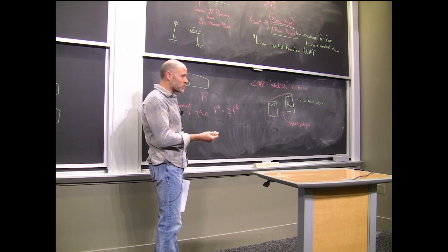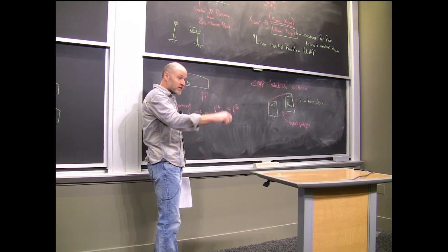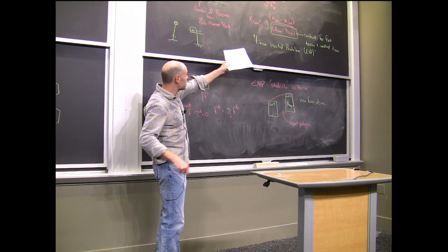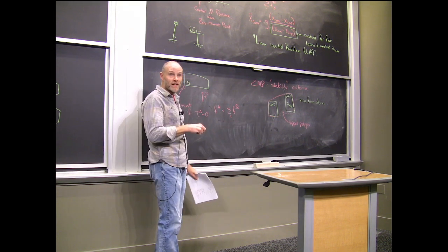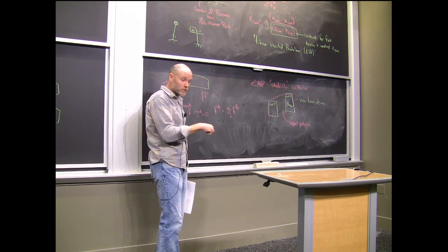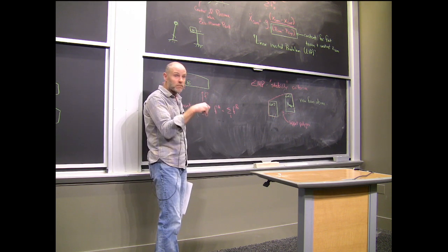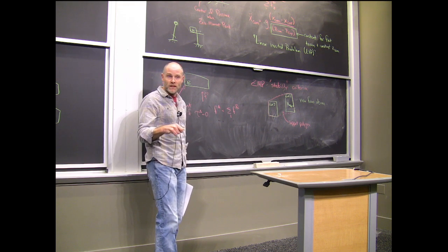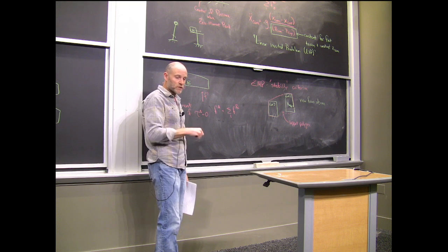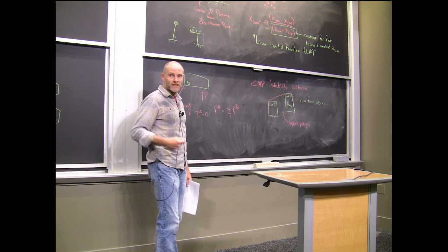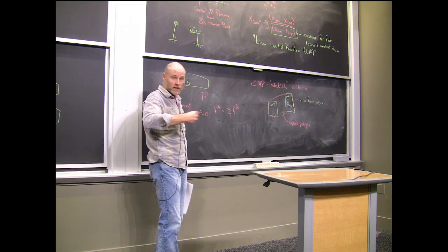Okay, so a natural thing to say: I've got a desired center of mass trajectory, and I have a controller which can move my center of pressure around to affect my center of mass. Or I could do the opposite. I could say I've got a desired center of pressure trajectory, and I'm going to move my center of mass around. In both cases, you have a linear dynamical system that describes that, and you can adjust for feedback. You can write an LQR controller, which you could again solve on the fly, or you could just solve it as an MPC kind of problem.